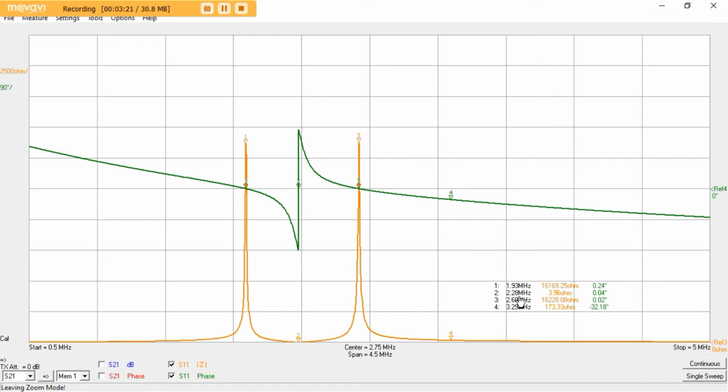I've got a 2 meter extension wire at the bottom end of the secondary coil. I don't have that connected down to the RF ground at the moment, but I'm lowering the impedance using that wire so that it is in quarter wave mode.